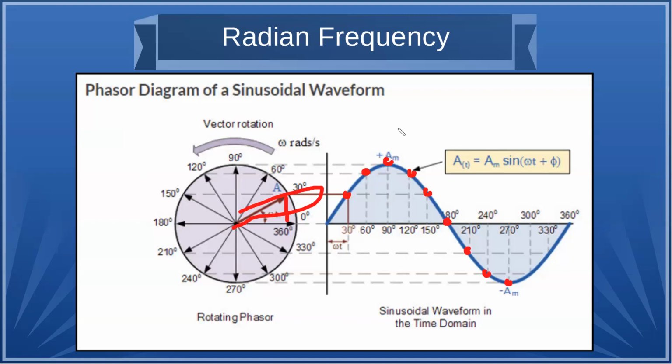So in a lot of the equations you'll see, you'll have a 2 pi f showing up. And that's where that comes from, is there's the frequency is how many of these cycles there are per second. The 2 pi represents how many radians per cycle. So if you have a fraction of a cycle, then you're going to get a fraction of 2 pi radians, like pi radians, pi over 2. Just so you know where that stuff came from.